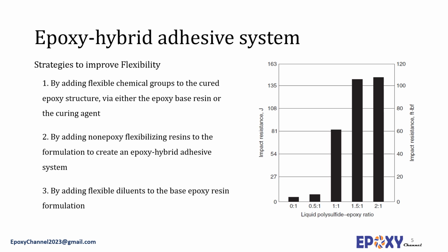We also have flexibilizers that are used as additives to rigid epoxy resins either during the epoxy formulation stage or during the epoxy resin manufacturing process. They are generally reacted into the epoxy resins or have reactivity with various curing agents so that the cured properties are not significantly reduced due to the addition of the flexibilizers. These techniques are often used in epoxy adhesive formulations.